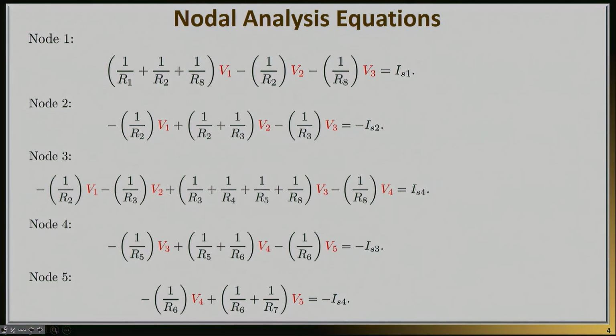These are exactly the same equations as you saw before, except that now I basically wrote some known coefficient times the first unknown voltage, plus some other known coefficient times the second unknown voltage, all the way until I have all the voltages in my node. And then finally, I have something known on the right-hand side. You can do this for every single node in your circuit. In this case, I have 5, and so I have basically done this for all 5 nodes.